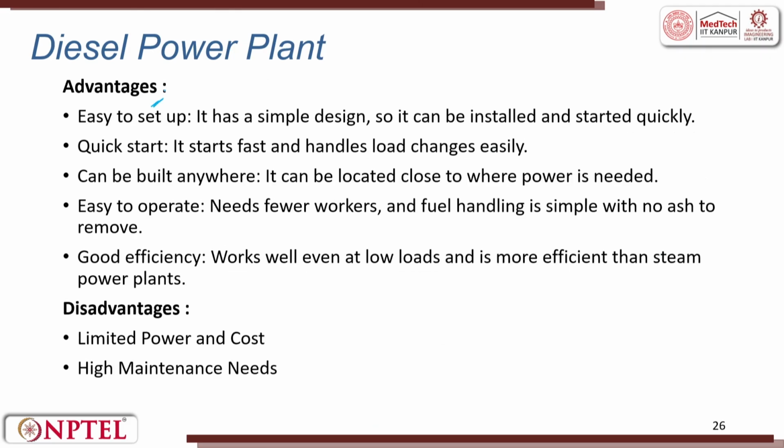The advantage of the diesel plant is that it is easy to set up and quick to start. Thermal power plant, nuclear power plant, hydro power plant: if switched off, to start again takes a long time. And hydro, if the water is drained, it cannot run. That is a big problem. So, the easiest to establish, quick to start, can be built anywhere, easy to operate, and with very good efficiency, is diesel. But the only thing is, it cannot go for very heavy power.